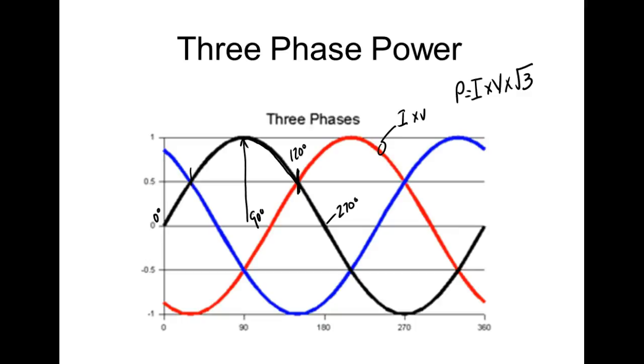And another advantage to it is that it automatically creates an electrical field that rotates. So if I put these 3 phases 120 electrical degrees apart, and then I put a big thing in the center, when this phase is going down, this phase right here is building up, and what does it do? It causes the field to shift. What that means is whatever's in here is going to rotate.